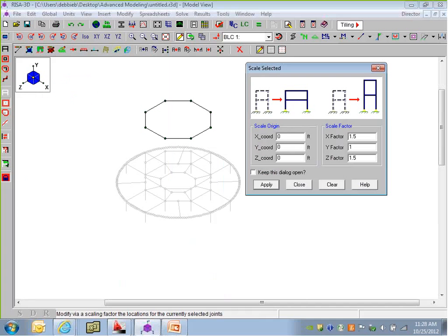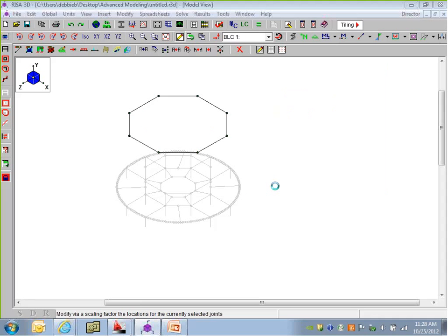What you do need to do, again, is make sure you remember that origin point. We said our origin is 19.5 and 144 feet. We can actually keep our 0, but I'll say 144. But the big key there is our 4.5 and 19.5. That's our origin, and I can say apply, and it will scale that up.